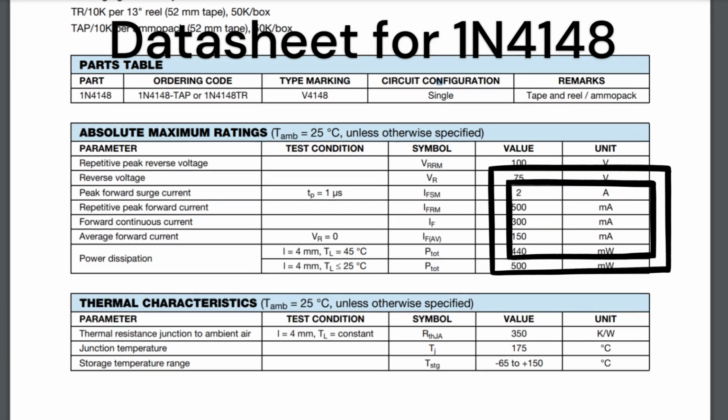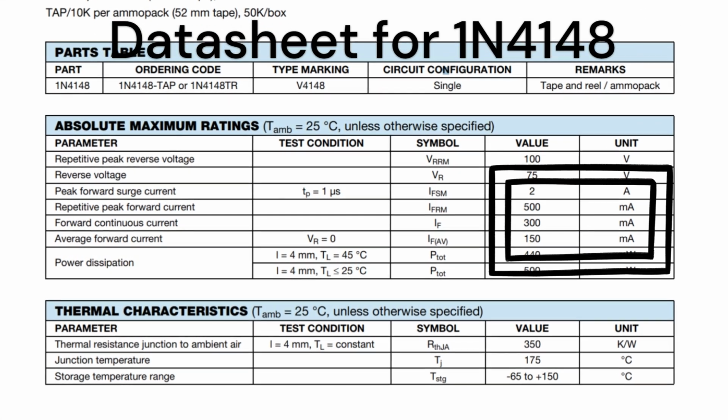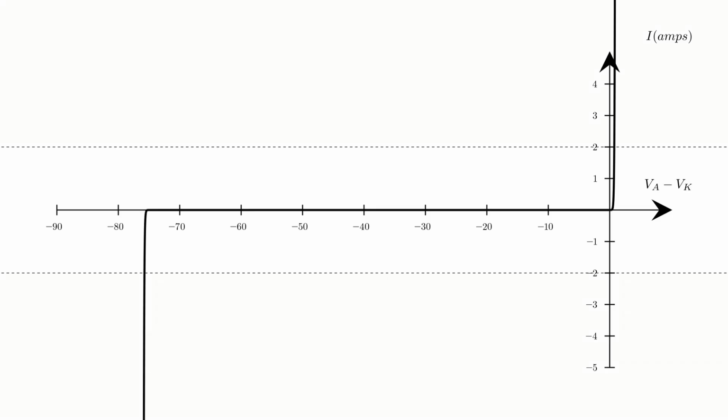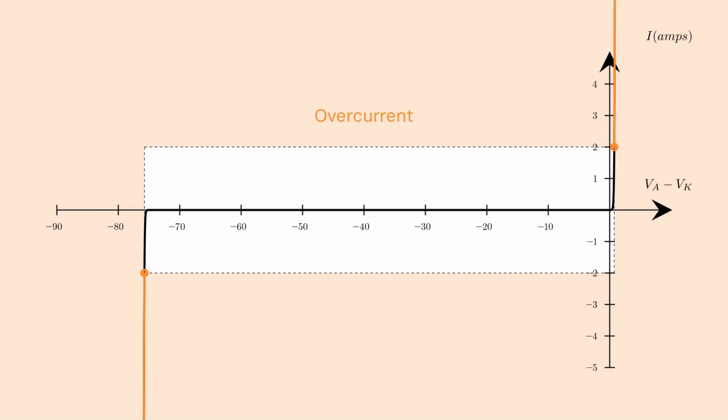Most diodes have maximum allowed currents both for the forward and breakdown modes. Too much current will overheat and damage the diode. Matching those with the voltage current plot, you get a complete bound for both current and voltages that you should keep the diode in to be safe. You must stay within the box to stop your diodes from catching fire.